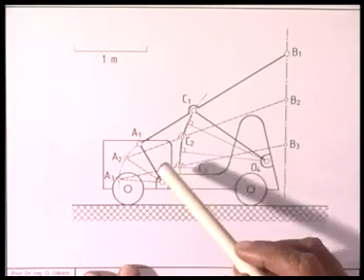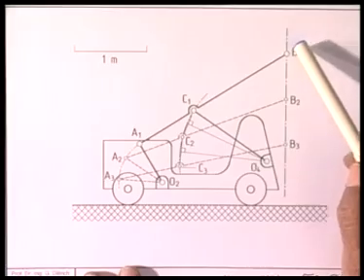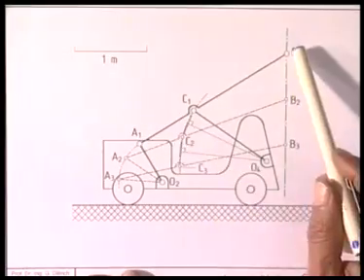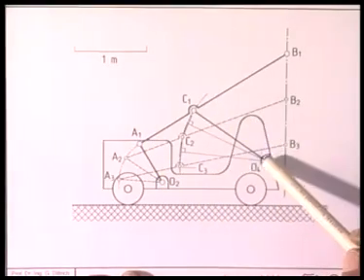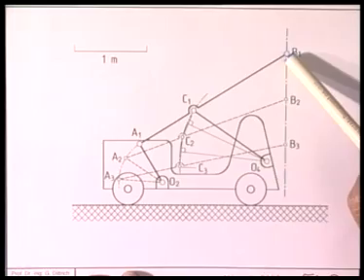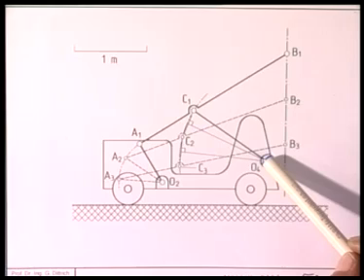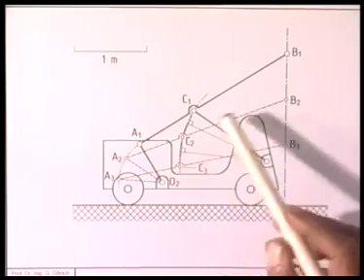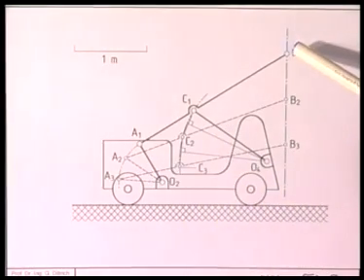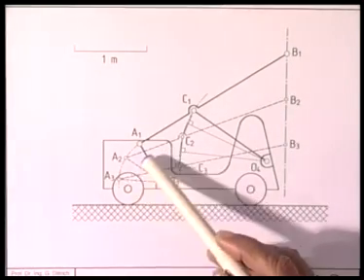So in the first stage, we have obtained this O2A1B1. Now I remove the slider at B1 and treat this link AB as the coupler of a 4-bar link, namely O2ACO4, and B is the coupler point of this 4-bar link O2ACO4. Our objective is, how do I determine the correct location of O4, so that when this 4-bar linkage is moved, this point B1 will automatically pass through B1, B2, B3, and maintain the coordination with the input movement.